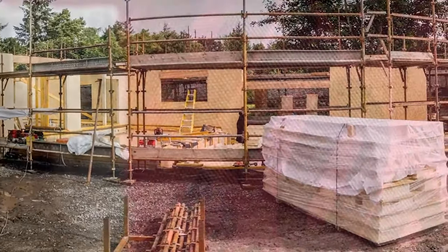The use of Wraptite externally delivered an air leakage rate of 0.64 metres cubed per square metre per hour, well below the Section 6 maximum recommended value of 7 and in line with best practice. This performance helps deliver a carbon dioxide emission rate over 30% better than required. This also gives EPC ratings of 94 for energy efficiency and 93 for environmental impact.